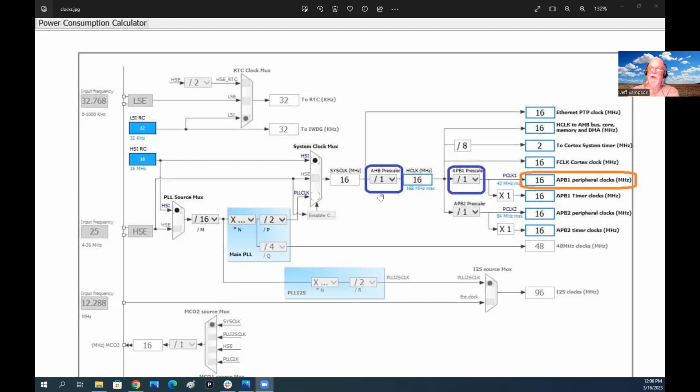And theoretically, if I spend enough time digging through, I can find where they're initializing the clocks. I can look at all these numbers. So it'll say it's using the 25 megahertz crystal, the external one. It says this mux will be set to this position. This is dividing by 25. This is multiplying by something, divided by something. And I can look at all these numbers all the way through and figure out what they should be. But there's no way, just firing up the board.